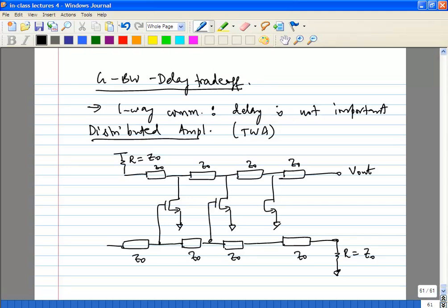So you're going to take a second tap delay line and put it at the gate of the transistors. This is your Vn. The main idea is this. Let's say at the input you can give a step input. After a certain delay, it arrives at node 1, gets amplified by this amplifier and goes to this node.